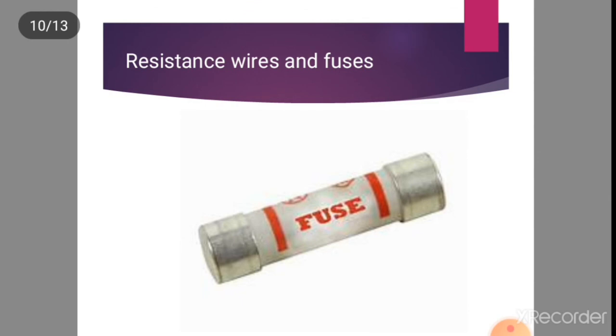A piece of specially chosen wire called a fuse can be put into a circuit so that it melts before the connecting wire. A fuse has a high resistance and therefore melts or blows when too much electric current flows through the circuit. The supply of electricity is cut off and the rest of the circuit, including any device attached to it, remains safe.